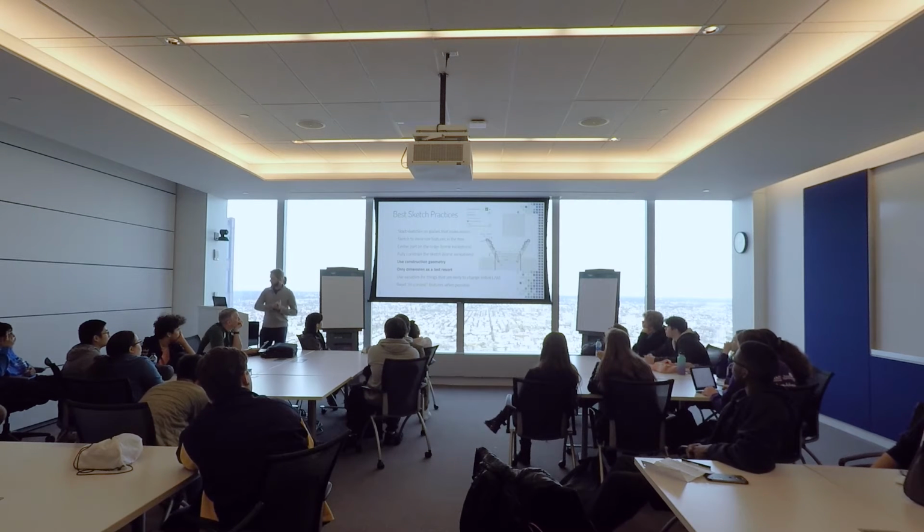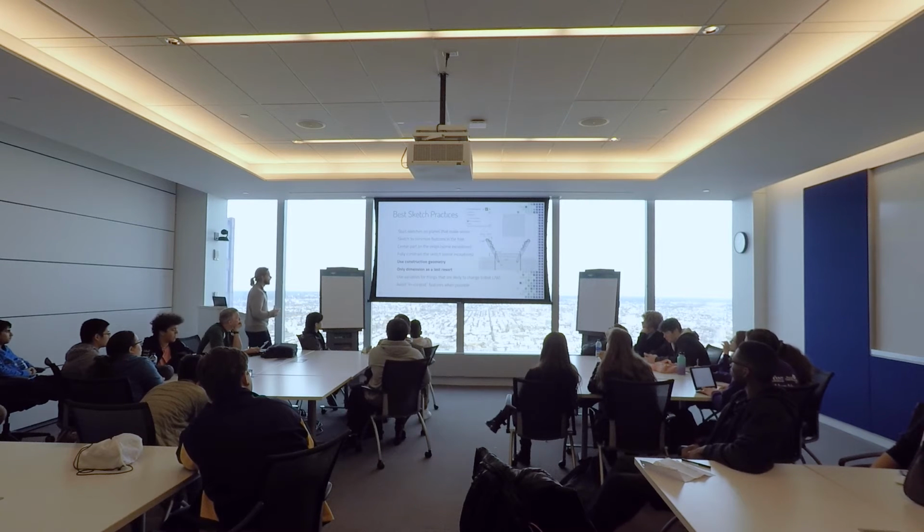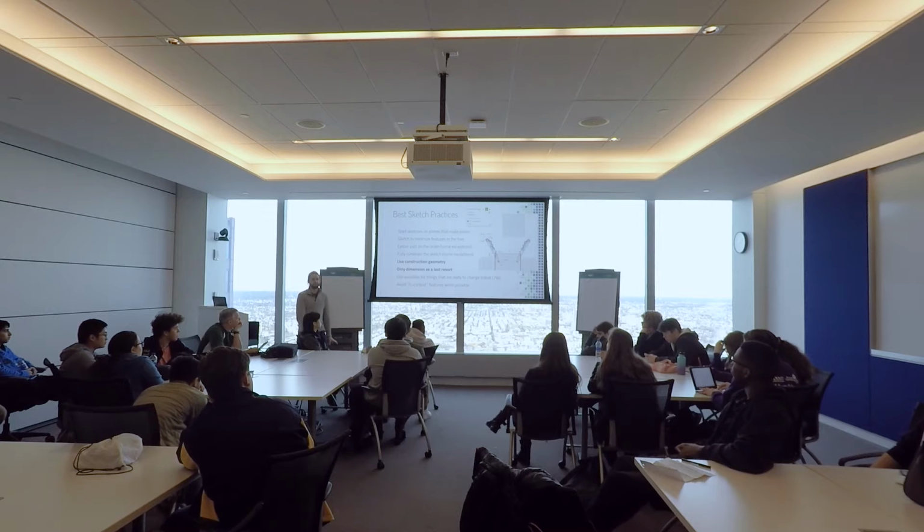I'm going to go into best sketch practices. The most important thing is, again, where you're starting. You want to have intent when you're designing in CAD. You want to think about how these things are going to work out as you're drawing them. So you also want to think about where you start these sketches. I usually say that my top plane is basically the floor when I'm drawing something in CAD.